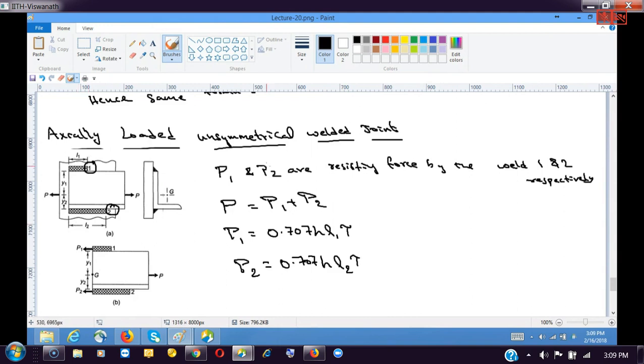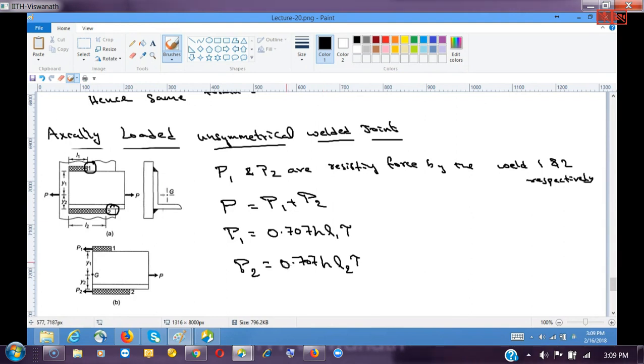So by this, we have satisfied the force balance. This force is compensated by forces P1 and P2. But in order to maintain the center of gravity the same, the moment about the center of gravity has to be zero. Otherwise, it would not make sure our center of gravity is unchanged.